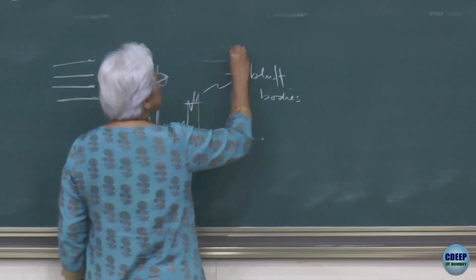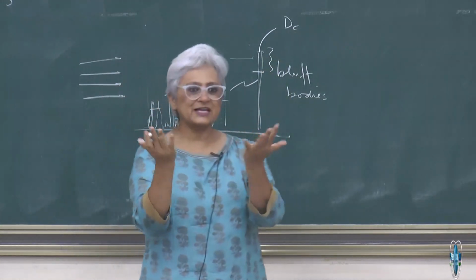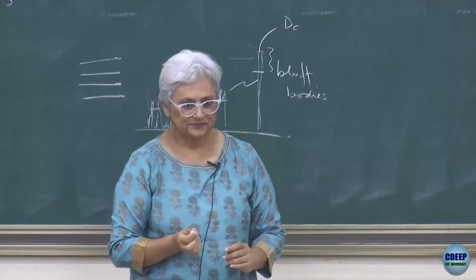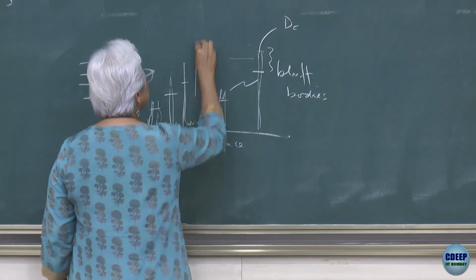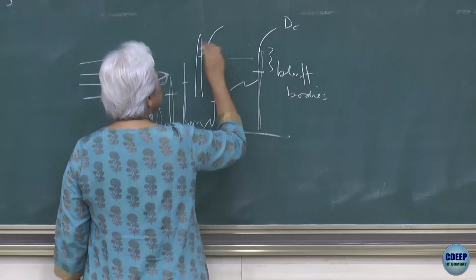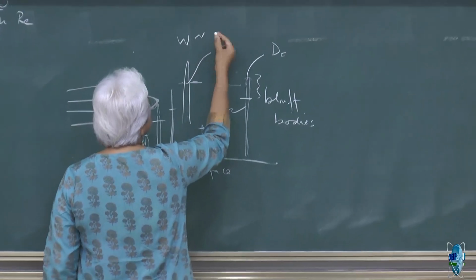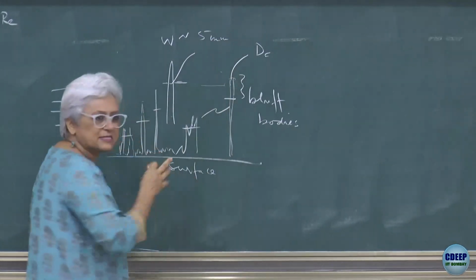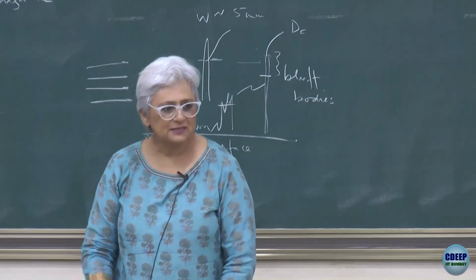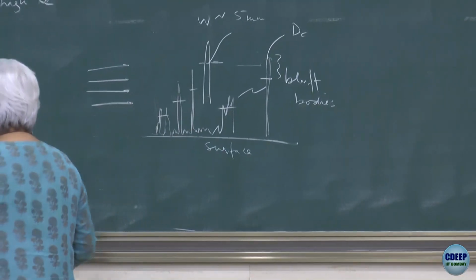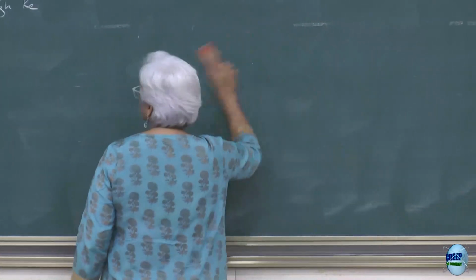But notice of course that it is the diameter of the cylinder which is still going to be the characteristic length, right. By the way, this is a cylinder, but it could very well be a blade of grass, and you could have the width of a blade of grass, which is of the order of 5 mm or 2 mm, being the characteristic length. So, this is the physical picture that we have with turbulent dry deposition to bluff bodies.